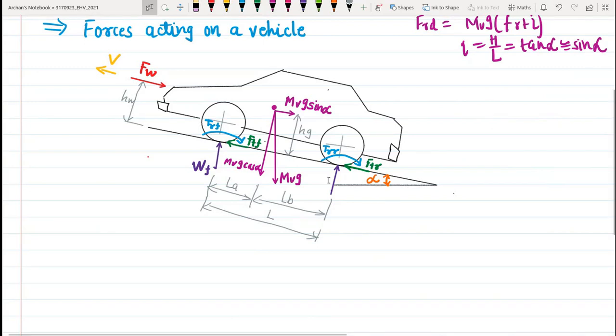Okay, so in the longitudinal direction, the major external forces acting on this two-axle vehicle include the rolling resistance of the front and rear tires. You can see it here with the green line, as FRF and FRR, and these are represented by the rolling resistance moments TRF and TRR.